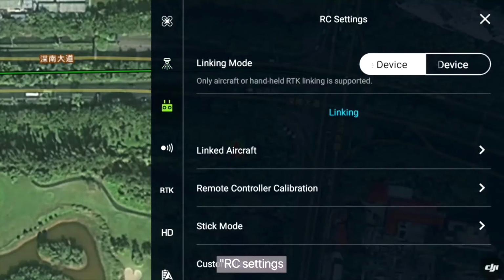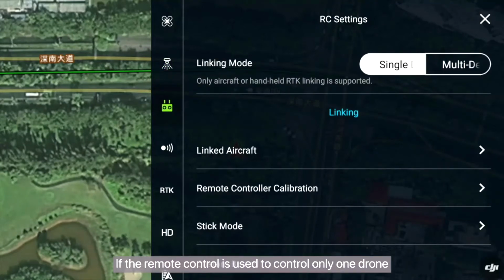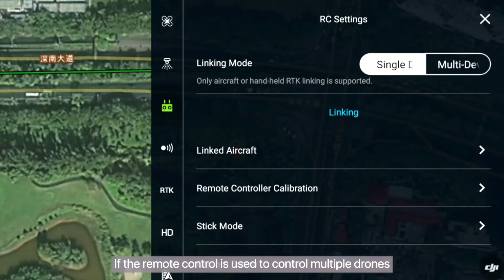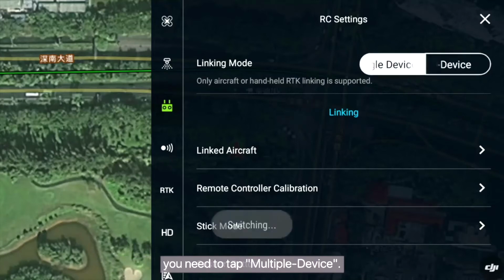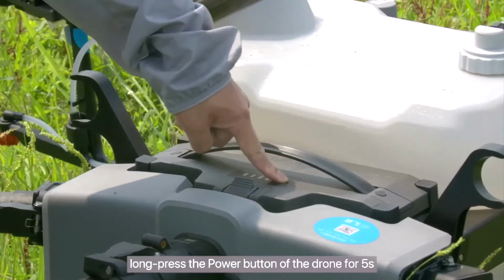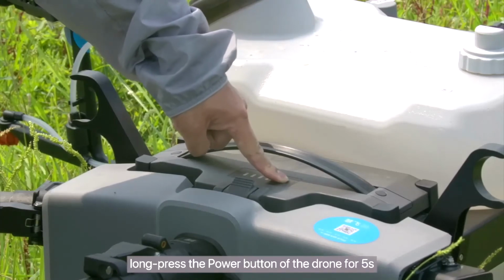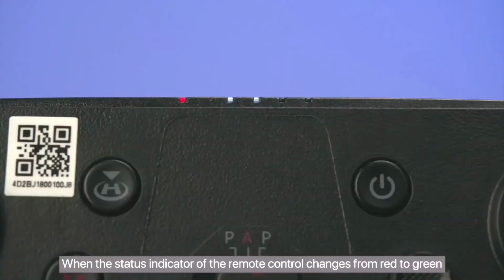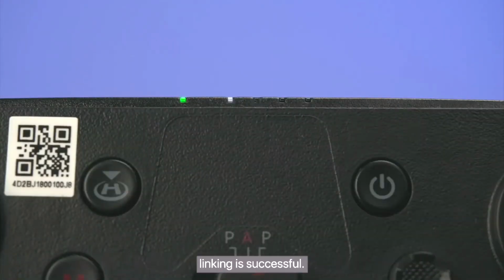RC settings. If the remote control is used to control only one drone, directly tap Linking. If the remote control is used to control multiple drones, you need to tap Multiple Device. Tap Linking to perform linking. Then long press the power button of the drone for 5 seconds when the drone is on. When the status indicator of the remote control changes from red to green, linking is successful.